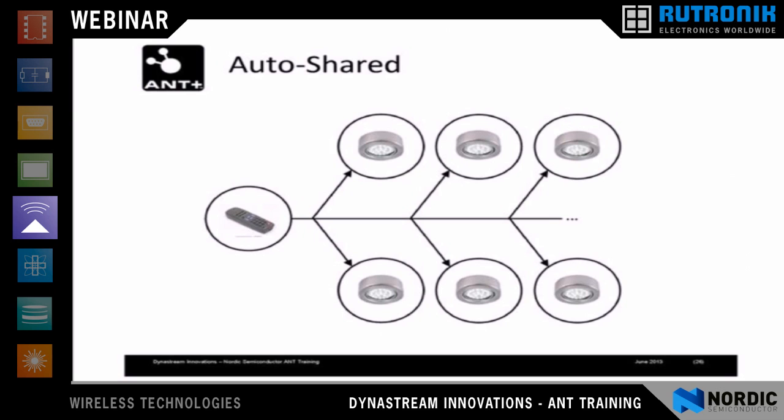Now you can make a connection with them using an application to turn them all on. And again, you would send a channel 0 onto that. You can see all the lights are on. You can turn them off again using that same address 0, or address, I shouldn't say channel. You can turn individual lights on. Again, there's light number 1 going on because the address has been sent as 1, as 2, as 3. And again, you can turn them all back off again.